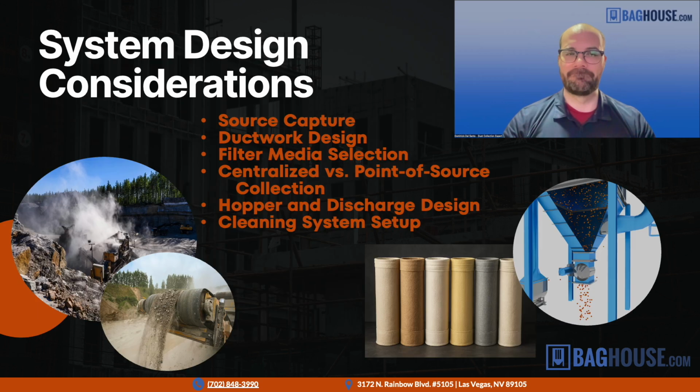Now, if we go to just a few points here about system design considerations, some of the most common things that we get asked that come up with regards to mining and cement applications are these. Source capture. In general, the closer to the source of the dust that you can put the pickup of the dust collection, the better it's going to be. If you try to vent a large area, it quickly becomes impractical.